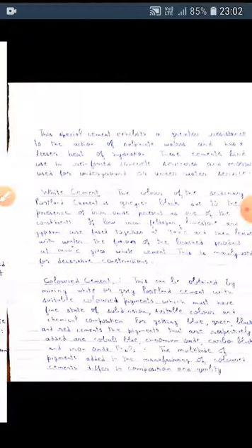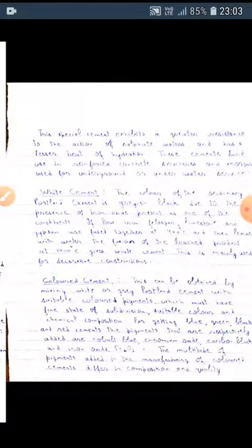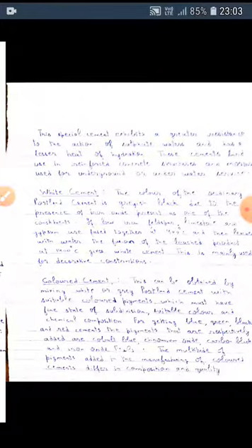The latter has a high light stability and resistance to weathering, alkali resistance, and acid resistance. The whiteness of cement is assessed using barium sulfate as a reference color. Its reflection factor is not less than 0.93. Whiteness is determined by the luminescence factor by means of a photometer.